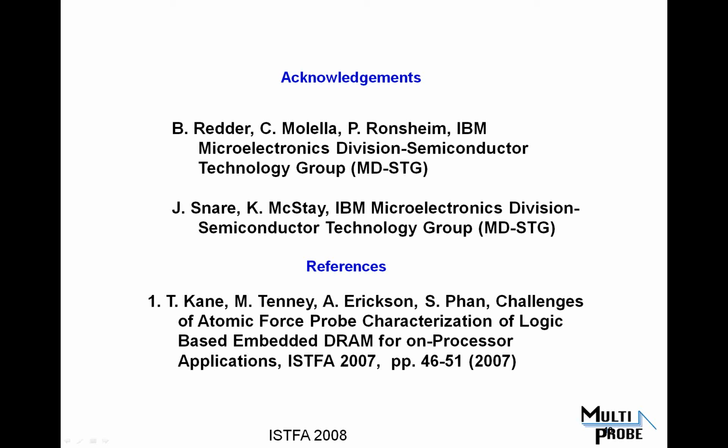So does your well contact have a body tie? There's no body tie. In other words, the body is floating. Well, I think what you're going to end up doing is grounding or applying bias to a source or a drain or to the gate itself, and then having a body contact, because I think the capacitance between the gate and the body is still the small one relative to the one that goes through the box layer. I'm not so sure about that. I think that's going to be an instrument setup. I think it's a tricky measurement, is what I would say.